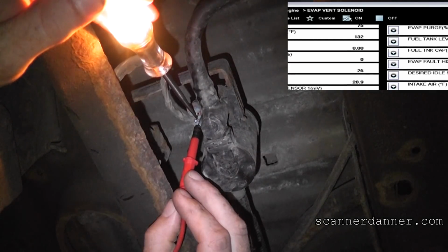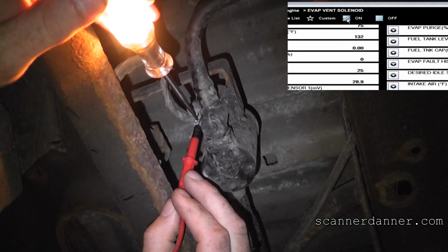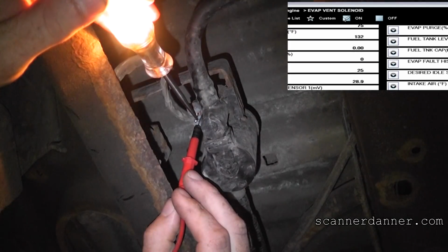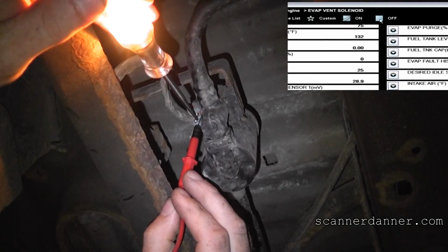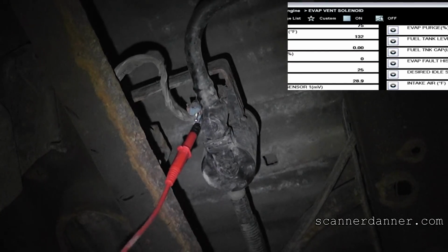Turn the driver off. Hold on, I've slipped off of it. Turn it on. Off. Keep doing that. How's my driver, guys? And how's my wiring all the way back to the solenoid? Okay, let me go back to the voltmeter now. Just so you guys understand, the driver's good. Yeah, you can turn it off.